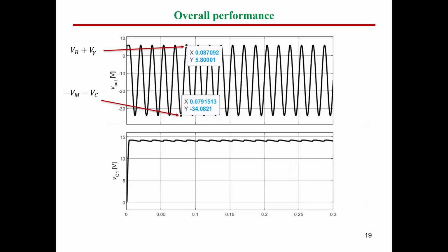For that, guys, that sinusoidal waveform, instead of having a peak of 20 volt, now has a peak of VB plus V gamma. So this is 5, V battery equals 5, plus the turn on volt. The turn on volt, according to the diode semiconductor material, can be, for instance, 0.6, 0.7, 0.8 volt. Here, in this case, we have 0.8 volts. So this is 5 plus 0.8 volt across the diode. So the peak value is 5.8, as you can see here.